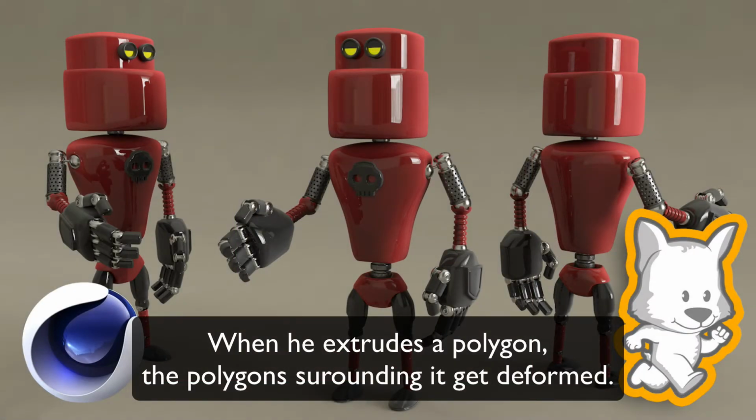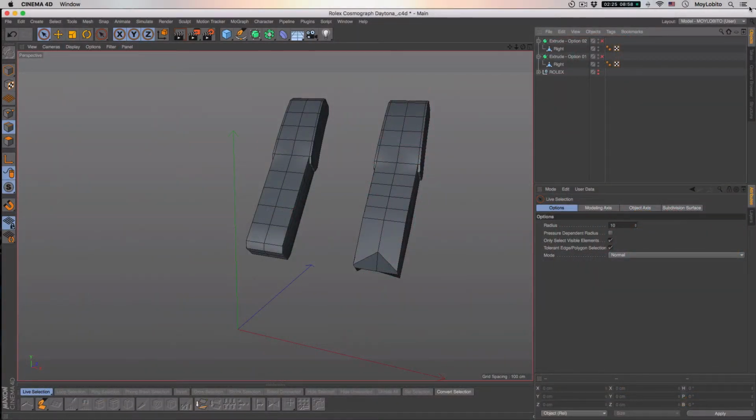Perfect. So now let's go back to our first question. And as you remember, my student said that when he extrudes a polygon, the polygons surrounding it get deformed. So I'm going to show you why I think that this happens. So what I believe was the problem with my student is that he just selected the polygons, he loaded the extrude tool, and he moved the polygons without making an extrusion first. So I'm going to show you how it works.